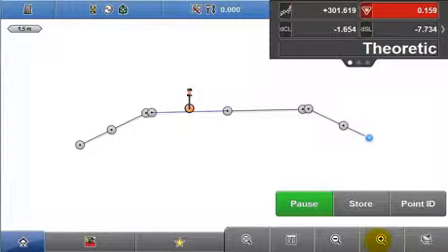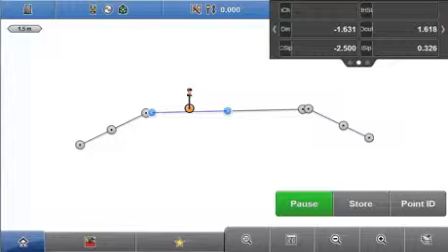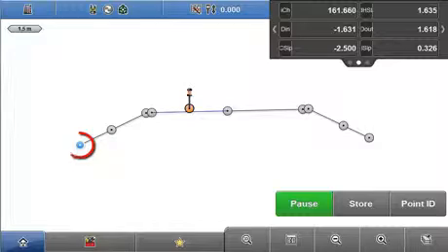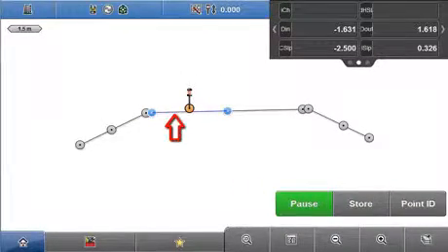Whilst in cross-section view, it's also possible to select a cross-slope to stake out by tapping it. The values in the info panel are explained in the Roading info panel video. To select a string line whilst in cross-section view, tap the point that represents the relevant string line. So there are 2 stakeout possibilities: stakeout relative to a specific string line, or directly stake out a cross-slope element.